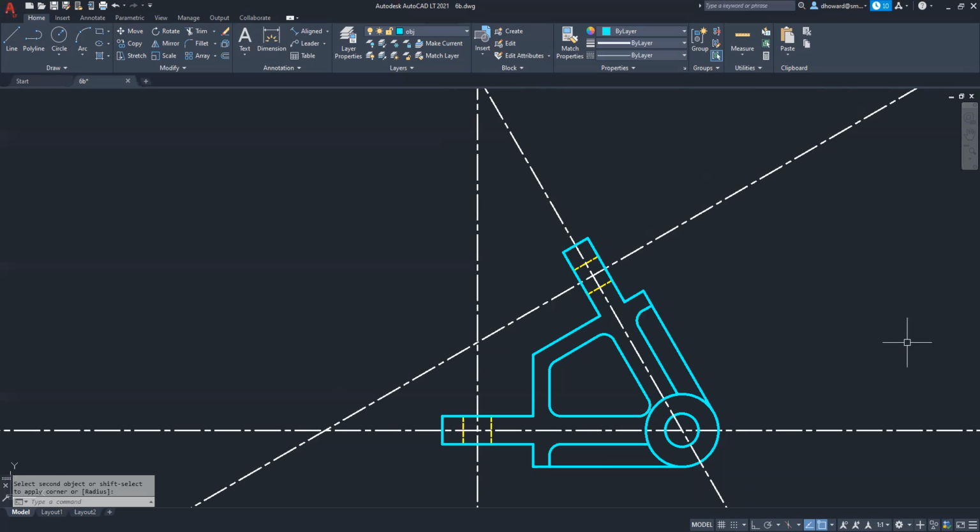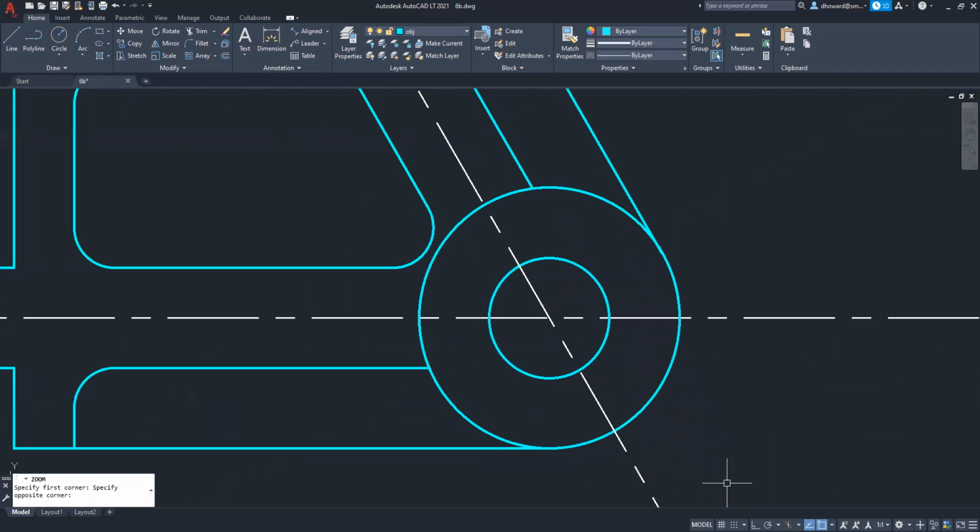So everything else is going to be just a little itty bitty 16th. Let's zoom in on that to do those. So if you come in close here, these guys are going to blend into the main cylinder here with the 16th fillet. So F, enter, R, enter, 1/16, and you can just go from here to there, and from there to there.